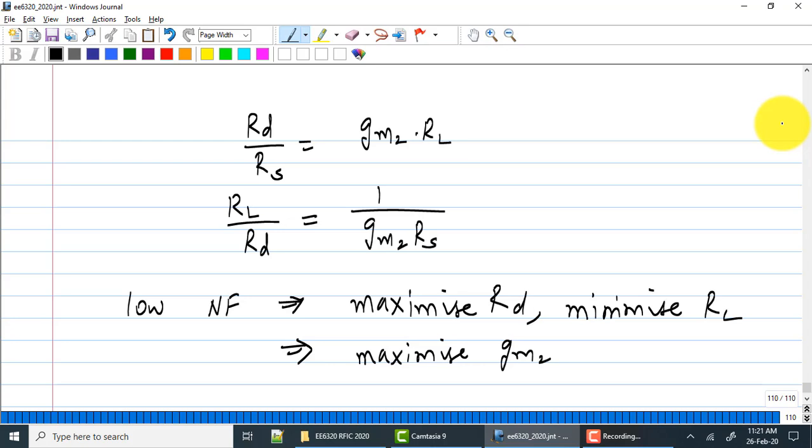So how do you make sure that this presents a symmetric output impedance? You probably need one more stage in between this and the following stage, if you want impedances to be matched well. How will you do that? You probably need a transconductance amplifier in between this stage and the following stage.